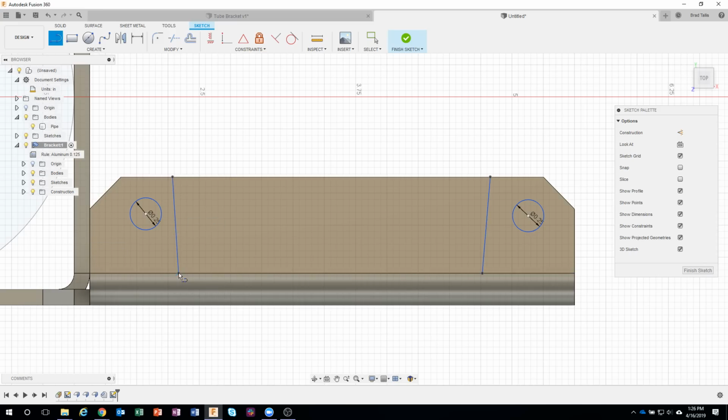Click and click. Now you might ask, why am I doing this? Well, I want to force it to be horizontal or vertical. In this case, obviously we want it to be vertical, so I'm going to click on that, and we can see that sure enough, that is vertical. I'll do the same thing there. Now you might say, well, that's a couple extra steps. Couldn't you have just moved your mouse until you got it to 90?